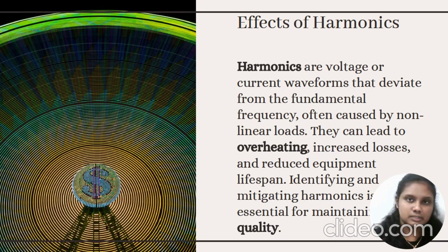Furthermore, I would like to explain the effects of harmonics. What is harmonics? Harmonics are voltage or current waveforms that deviate from their fundamental frequency, often caused by nonlinear loads. They can lead to overheating, increased losses, and reduced equipment lifespan. Identifying and mitigating harmonics is essential for maintaining the power quality.